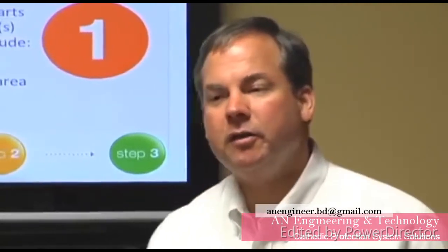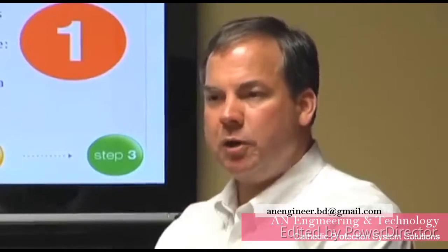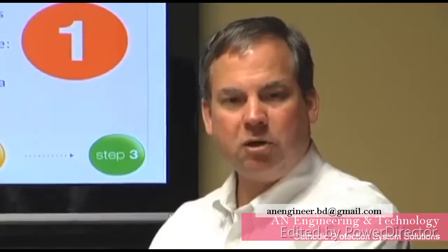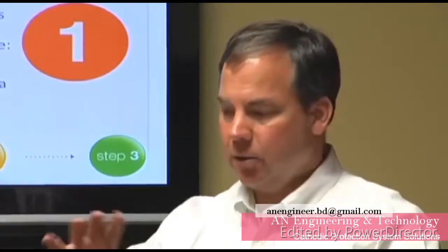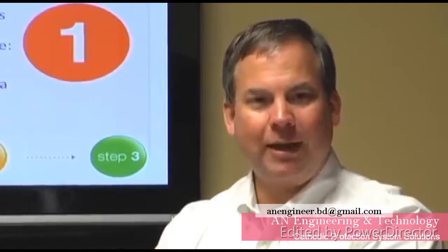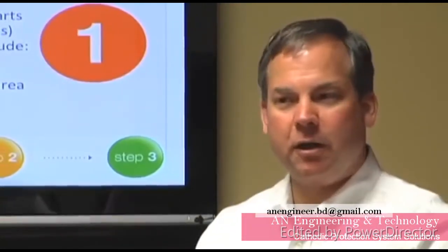Is it electrically continuous? You have some structures where there may not be electrical continuity between different parts of it. Ductile iron pipe systems are really bad for that, because there's a joint of pipe, a 20-foot joint. It's got a little bell to it. The other end's got a spigot to it. They push them, pressure fit them together, and they put a gasket between them. Well, that gasket can cause electrical isolation, so you may not have continuity between one section and the other.